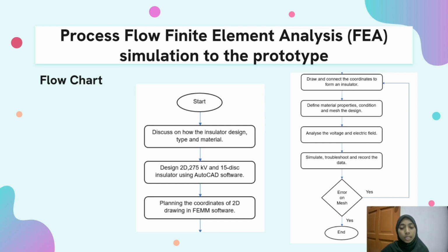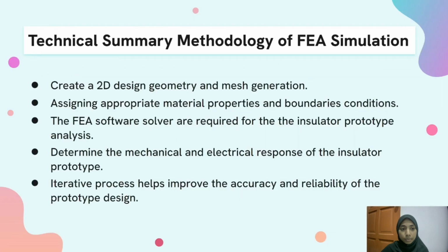Analyze the voltage and electrical field. We simulate, troubleshoot and record the data. If there is an error on the mesh, we have to check the connection and the coordinates from the insulator, and then it's the end. So, for the technical summary methodology of FEA simulation, first, create a 2D geometry and mesh generation.